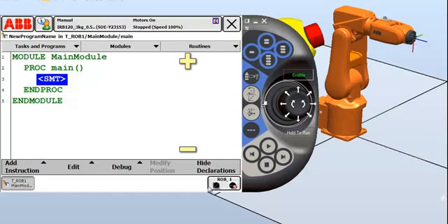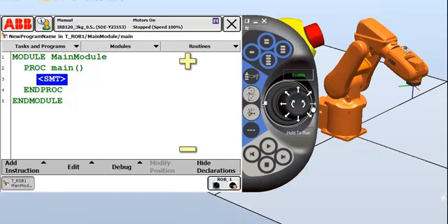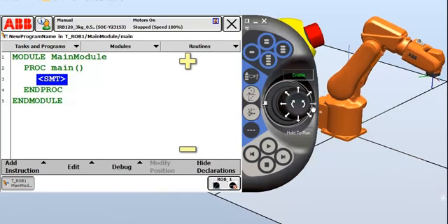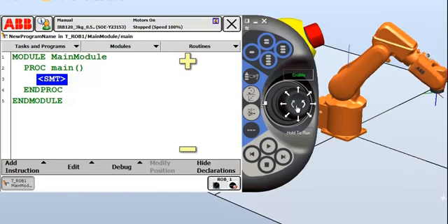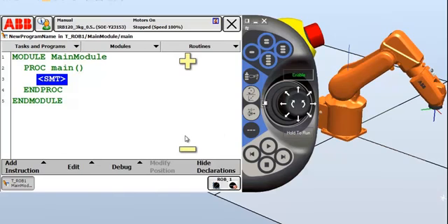So we'll start moving the robot down towards the pickup location. We are in linear jog mode and we have no increment. And remember, screw the lid on, so we'll go down. And it looks like we're just above the pickup location there. Obviously, when you're doing this with the real robot, it'll take a lot more time than this to move into position.